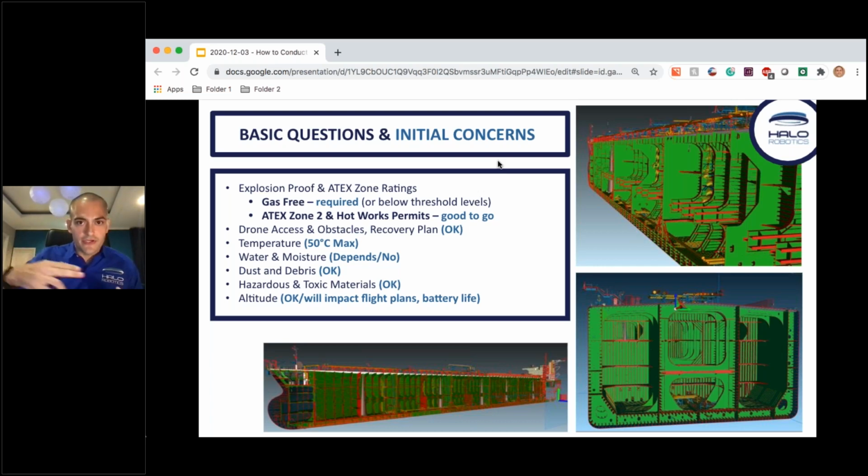For example, if we enter into a gas stripper where there are plates at different levels within that pressure vessel, what if we get stuck, or how are we going to deal with that? That definitely is something to address. The number one way to address this, and Charles will also discuss this, is preparation. What is the recovery plan? What are the emergency scenarios that we need to attend to?